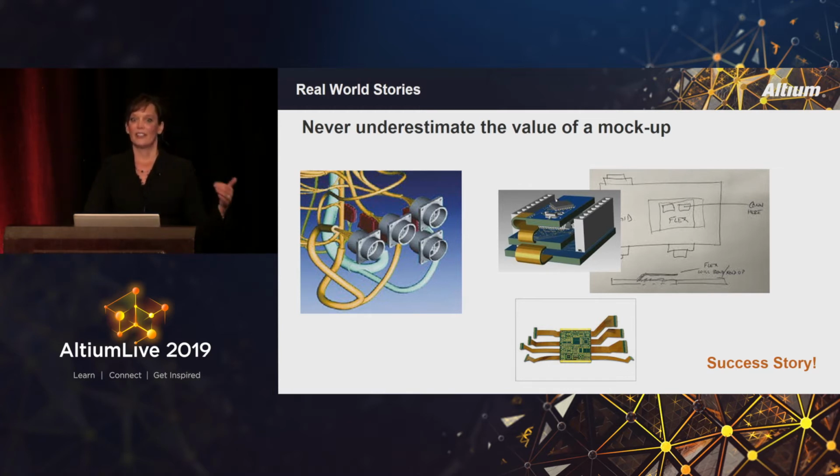And these were all interconnected with impedance-controlled 3-layer rigid flex that were thick enough that they were violating, or going to violate, all the bend radius recommendations. So going into this already knowing there was possibly going to be an issue, the program manager and the designer planned in extra time and extra money to actually go to the fabricator and get a mock-up of that flex, which I thought was a great idea.